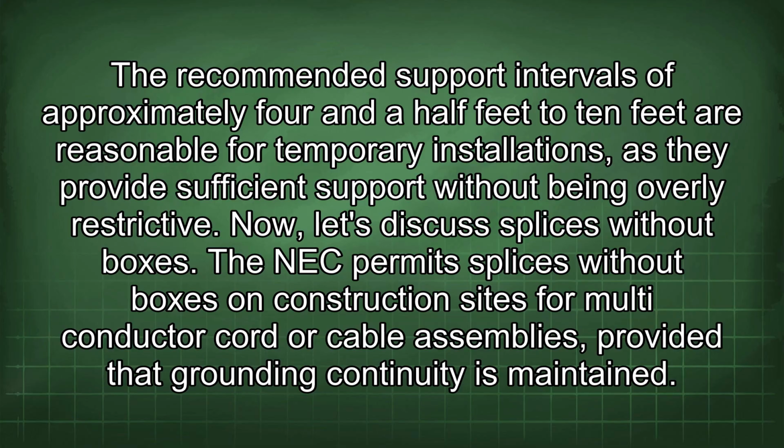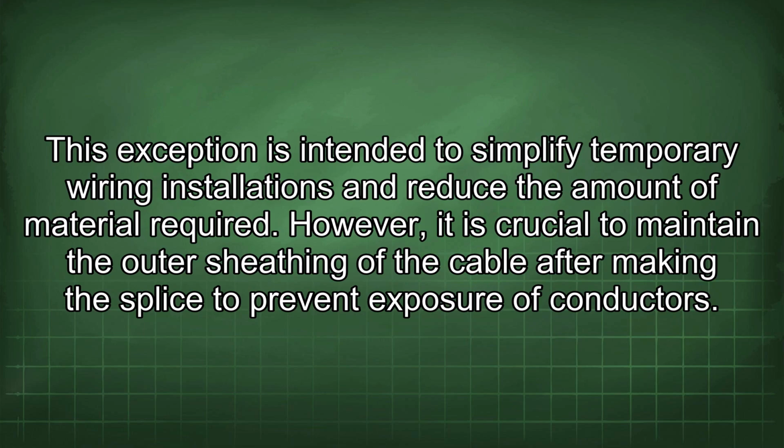Now let's discuss splicers without boxes. The NEC permits splicers without boxes on construction sites for multi-conductor cord or cable assemblies, provided that grounding continuity is maintained. This exception is intended to simplify temporary wiring installations and reduce the amount of material required.